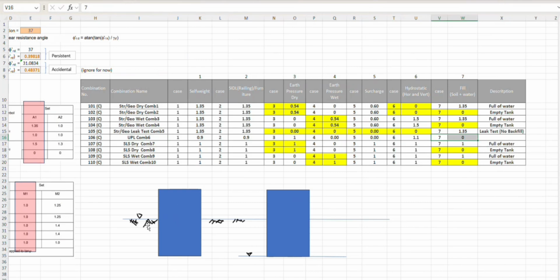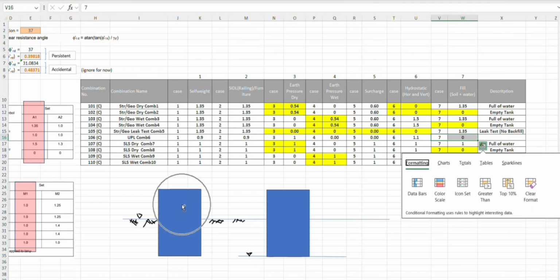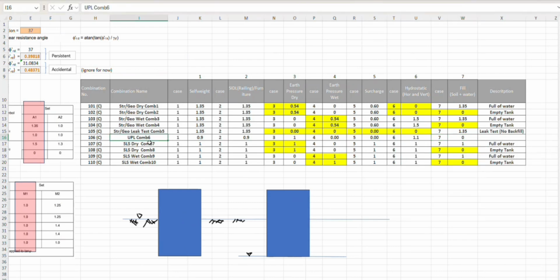And then your earth pressure, or you're considering this case over here where the groundwater reaches the ground level, so it's fully saturated around and you have a very high uplift pressure at the base, and you don't have water inside that resists basically the uplift pressure.